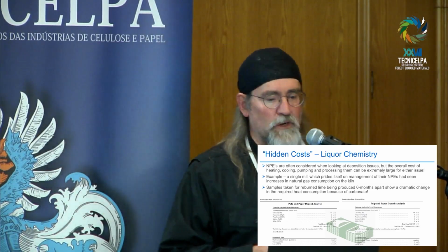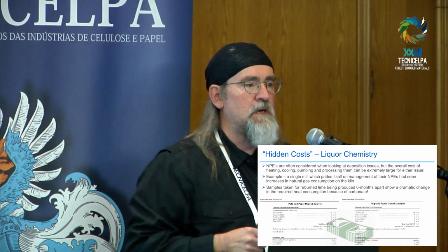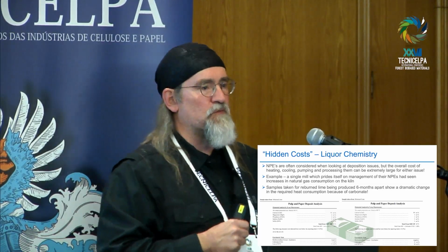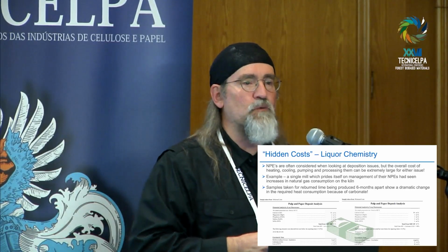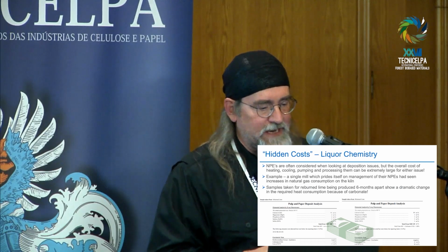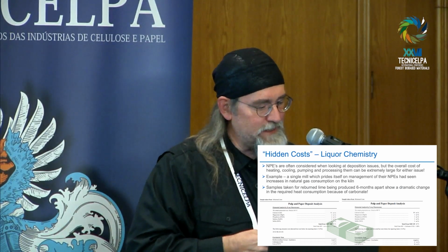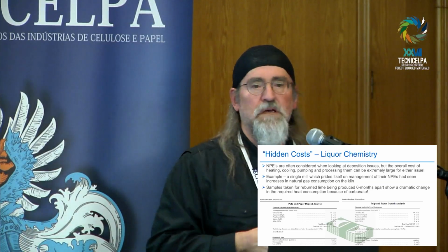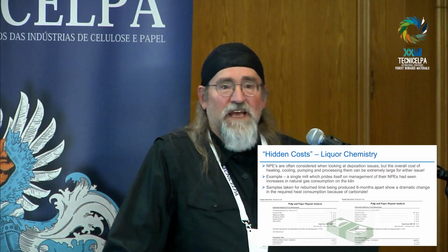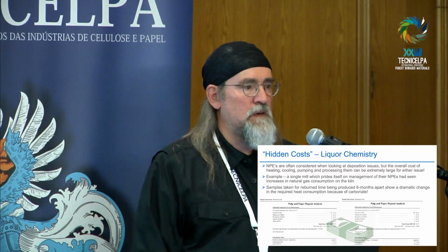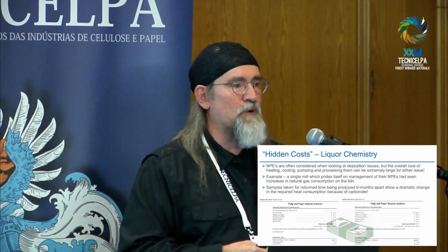So, again, what should we do about that? We want to improve it a little bit. There's money there. I want more lime in my lime. So how about if we work on temperature profiles and fix some of the things they did? And the more they worked on it, the worse it got. They got rid of magnesium. They got rid of phosphorus. They got rid of sulfur, you name it. Their availability went down to 84. Okay? I lost 7% lime in my lime by trying to fix a non-process element problem that wasn't a non-process element problem.